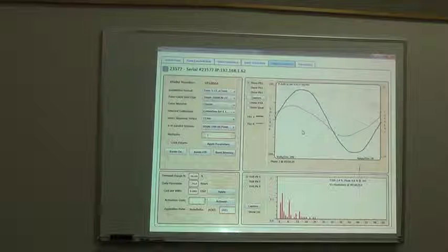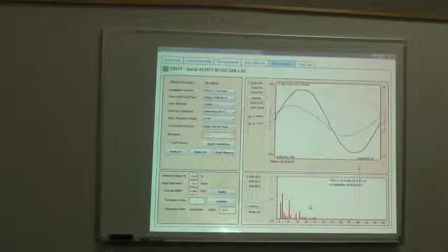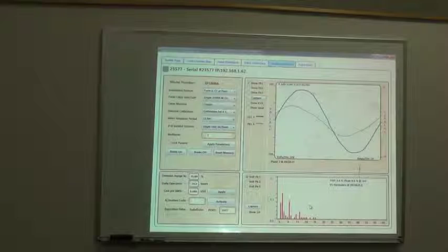That's not a problem because you just don't have the spectrum to look at. Actually, the spectrum of the harmonics on the chord, is there any value to it or no? Graphically, yes, there is. Because we can look at it and say, okay, we got a lot of computer load, a lot of drive load, or not much drive load. Or we got some weird thing out here at 47, we need to figure out what's going on.